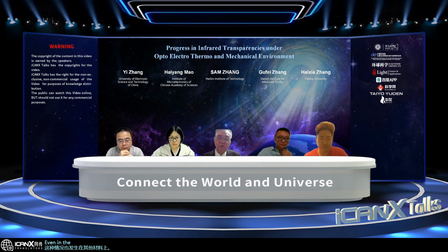This happens also on other materials. We notice that for high entropy alloy thin films and high entropy alloy bulk material, if you compare them, I have data to show that the thin film or coating of high entropy alloy is 2 or 3 times higher in hardness than the bulk. The reason actually is that the bulk material has much more deficiencies.